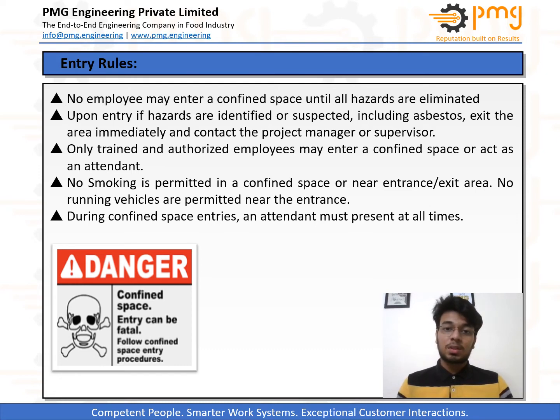The entrant must not smoke while inside and no running vehicle should be present near it, as it can lead to explosion or other very serious accidents. Any attendant must always be present near the entrance and should always be in touch with the entrant. That is very important.